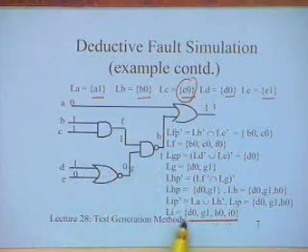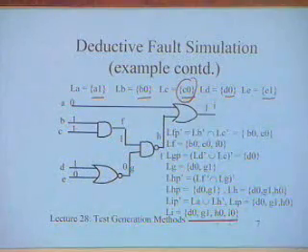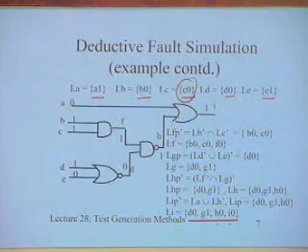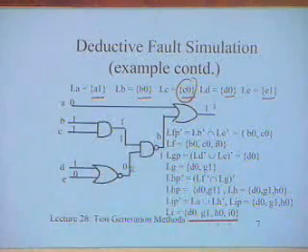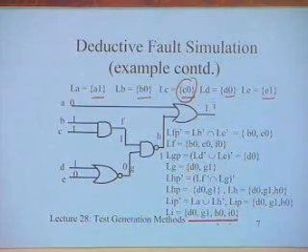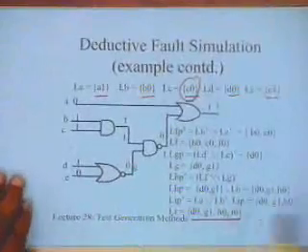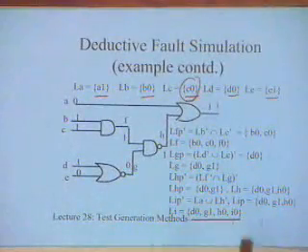So one of the primary input faults D0, G1, H0 and I0. I cannot detect faults at other places that are there. So 4 faults can be detected. If you are really comparing test vectors, as I said, the overall problem remains: what we are really interested in is identifying a small set of test vectors which can detect a large number of faults. So if I compare this test vector with the other test vector, I am better off with this because this can detect 4 faults while that could only detect 2 faults.